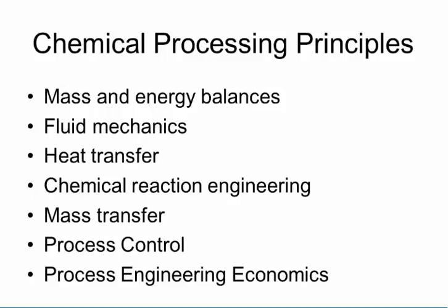Now, what are the key principles? Why is a process engineer important? Because one of the key things that we do is provide the mass and energy balances. Once we do the mass and energy balance, we have everything provided. So that is always a challenge. We need to understand fluid mechanics. Why? Because we need to determine the pressure drops. Understanding the concept of pressure drops will allow us to determine the pipe size.